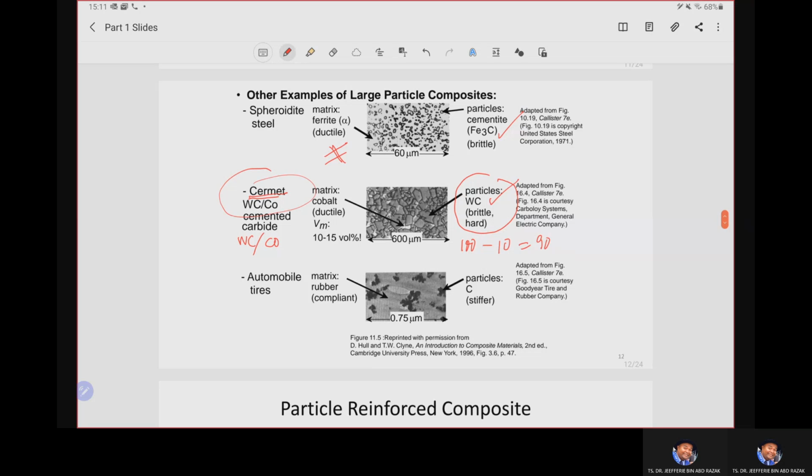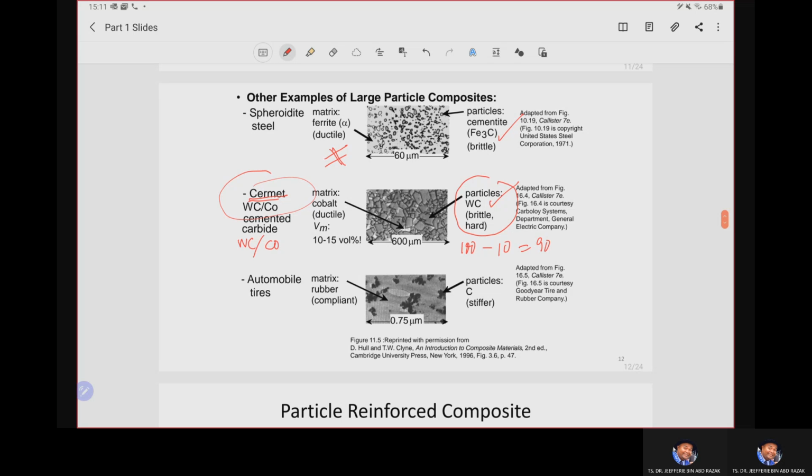The next common example is the automotive tire, which is made from natural rubber reinforced with various particulate materials. As you can see on your car tires at home, they basically use rubber, but we understand the rubber material is basically soft and very tacky. So without the reinforcing particulate material, the natural rubber based tire is not able to perform its function. The carbon black we add here is a fine particle obtained from hydrocarbon combustion, basically responsible for increasing the toughness, the stiffness and also the abrasion resistance of the rubber, for better rolling performance of the tire, especially on the road.